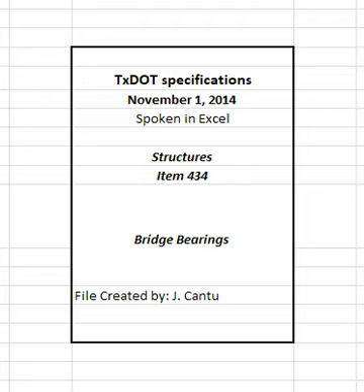Perform required welding in accordance with Item 441, Steel Structures. Manufacture guide bars, when required, so adjacent top and bottom bar surfaces are parallel to within 1/16 inches in the assembled position. The tolerance for diameter of anchor bolt holes is plus 1/8 inches, minus 0. The maximum deviation for flatness of steel plates is 1/16 inches in any 24 inches or as shown on the plans.